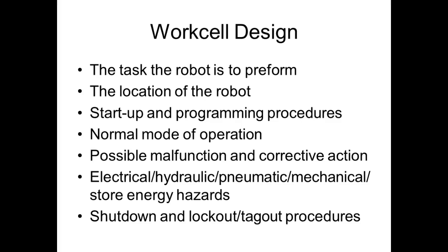Normally, robots use at least two sources of power. They probably use electrical power, and they probably use fluid power. The problem with electrical actuators, like motors, is they don't like to be stalled. They don't like to be forced to stop while energy is applied. Most electric motors, if you stall them, will burn up. They're not protected. Fluid power doesn't care. So if I want to leave pressure on something 24 hours a day, I'm not going to do it with electric motors. I'm going to do it with fluid.